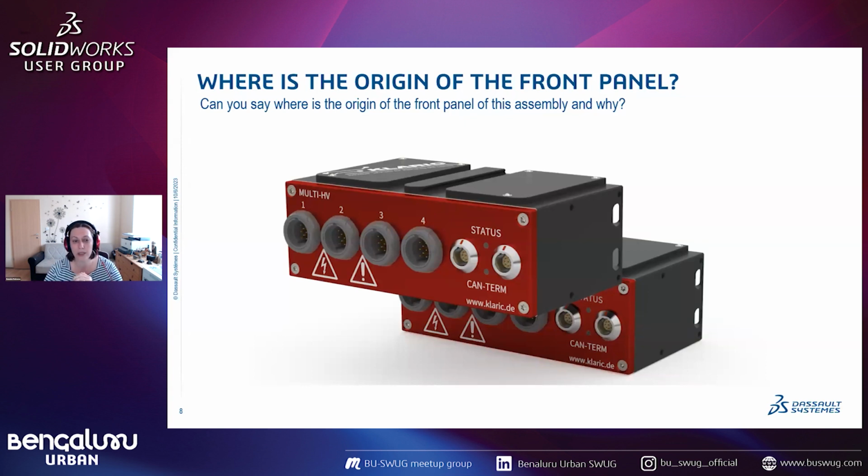In this case, however, the origin is the bottom corner, not in the middle, not because it's easier to design like this, but because it's relevant to all the models which are inside this assembly. This assembly is a combination of mechanical parts and a lot of boards, and all the things should have exactly the same origin point. So it's not just the front plate and the housing that are made with the same origin. It's also the boards inside. Because if the connector is in the wrong position on the board inside, it won't fit on the front, or the board won't fit in the housing.